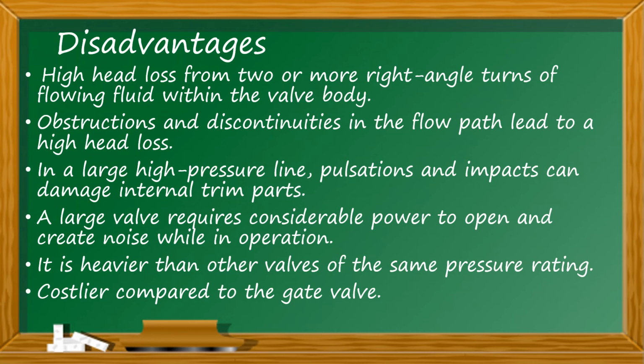A large valve requires considerable power to open and creates noise while in operation. So if we use a large capacity globe valve, it requires much power and also creates a little bit of noise. It is heavier than other valves of the same pressure rating, so that is another concern. It is also costlier than the gate valve. That is why I said that the gate valve is preferred to the globe valve if there is no pressure drop concern at all.